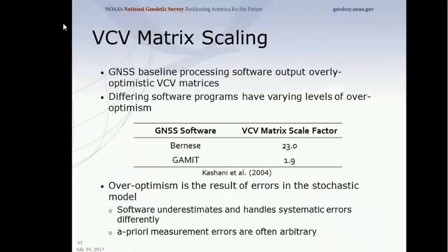So you would think, okay, you've built your network, now just adjust it. It turns out there's one more detail we had to work through, and this is actually a pretty big problem, and I hate to even mention it. It's so important, though, that I have to: we're combining vectors from two different sources. We have one source from the RTN and the other from Opus Projects, and it turns out the variances and covariances of each of those vectors are drastically different.